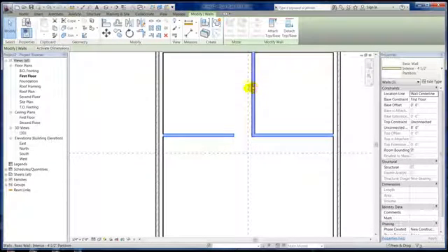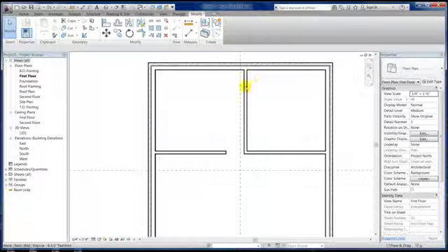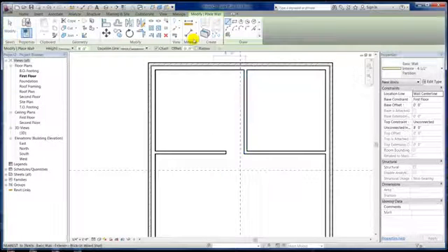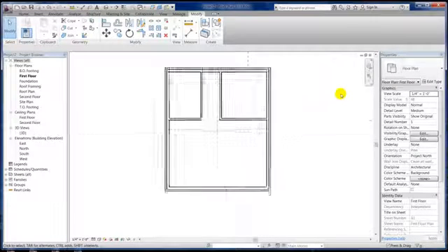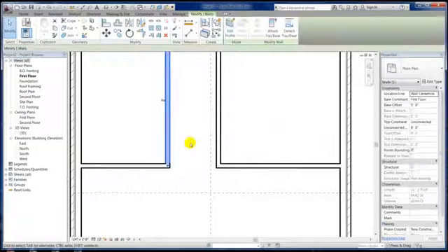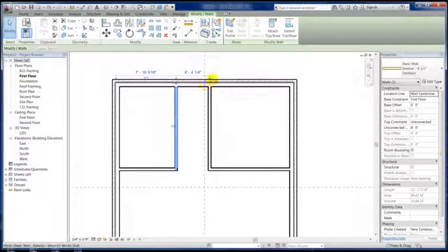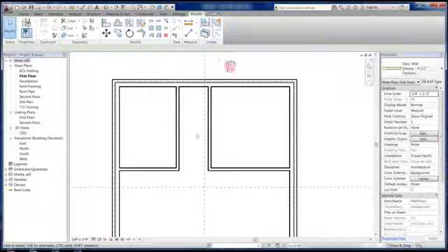just like I created these walls off this plane, I can create this wall and do an offset. Let's say 4 foot, let's call it 4 foot 2 inches, and there it is. So you can offset off a wall, you can offset off a reference plane. There's a lot of things you can do. And then again, you want to double check your dimensions. See that also, I want it to be 4 foot 2 inches instead of 4 foot 4 1/4. So there's my hallway right there.